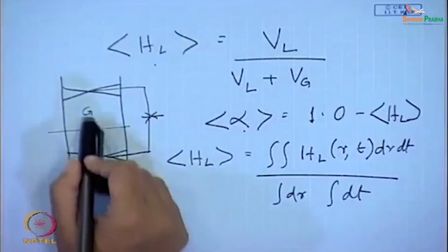We would always like to define the in situ composition in terms of the volume fraction. But remember one thing, this has to be measured. This cannot be controlled by us, this cannot be an input, and no flow meter directly gives you the measurement of the in situ composition, isn't it? So, it may not always be possible to measure the volume average composition. Why? Because as I have shown to you, to measure the volume average composition, what do we have to do?